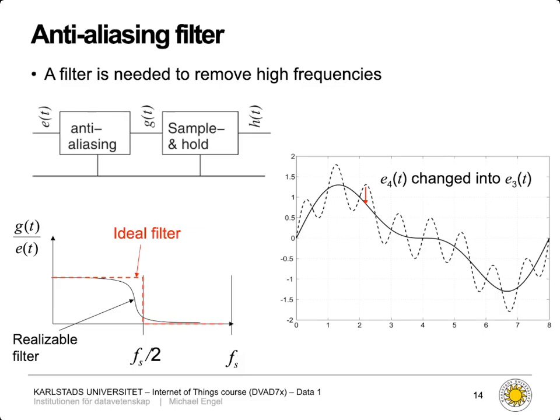So, for example, this would mean frequencies that are closer to our sampling rate in an audio signal are not as loud, so the amplitude is going down. And then what's maybe even worse is that we have still parts of the amplitude on the right-hand side of half of your sampling frequency. They're pretty quiet if we have an audio signal, but they still exist. So it's just approximating 0, but it doesn't reach it there.